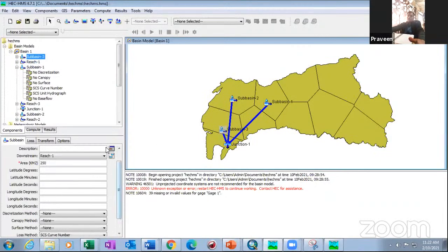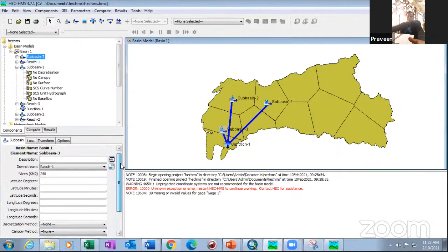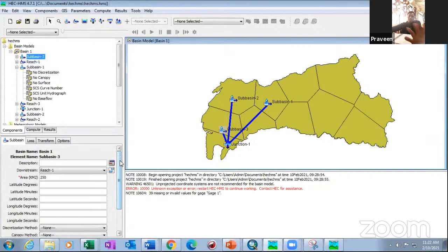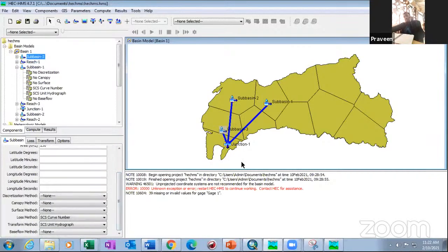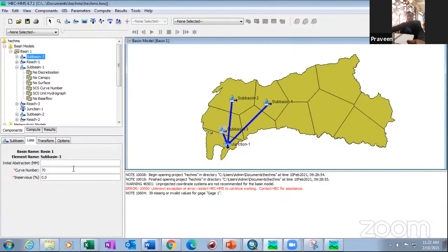Okay, fine. So I hope everyone will try to fill those values. If you open HEC-HMS, just try to fill these values. I'll give you 1 minute. For the area, you can put any random area. Okay, we are just practicing. Then put the loss method, SCS curve number, and the transform method, unit hydrograph. There you also define the curve number and the transform method lag time. I'll just say 120 is the lag time. We computed the lag time using the Kirpich formula, so we're just defining.